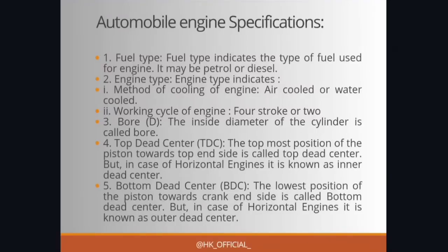The fourth and fifth are very simple for us, that is TDC and BDC, top dead center and bottom dead center. We all know what top dead center is. The topmost position of the piston towards the top end side is top dead center. And what is BDC? The lowest position of the piston towards the crank end side is your BDC or bottom dead center. So these were 5 specifications.